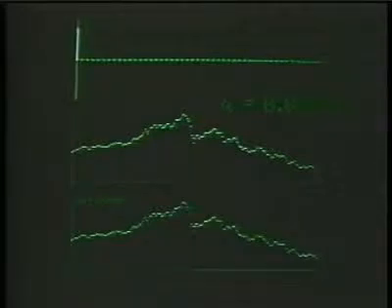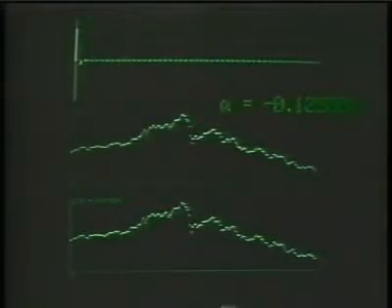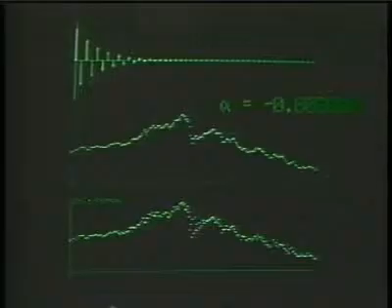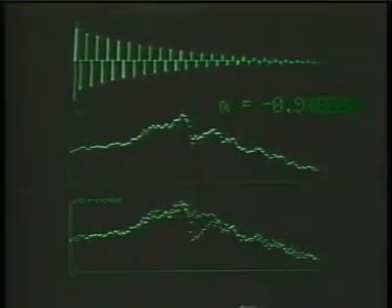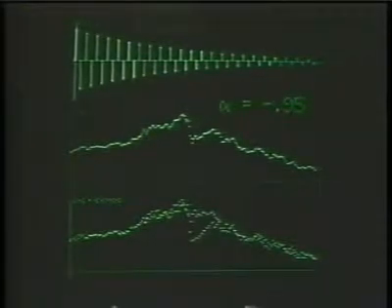All right, now we want to continue to decrease A so that it becomes negative, moving from 0 toward -1. And what we will see in that case is more and more high-pass filtering on the output in relation to the input. And this will be particularly evident in, again, the region of high frequencies represented by sharp transitions, which, of course, the market crash of 1929 would represent. So here now A is decreasing toward -1. We see that the high frequencies or rapid variations are emphasized.